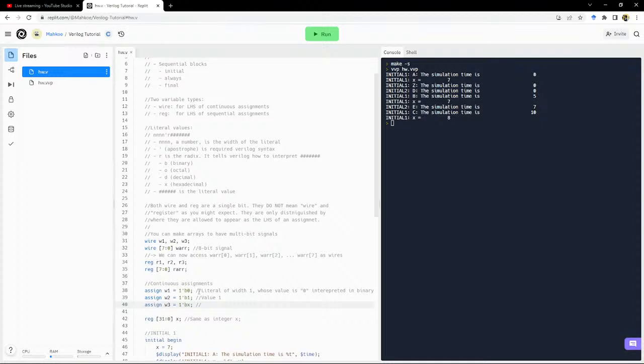Well, in Verilog, wires can have value 0, 1, X, or Z. Now, a 0 and a 1 mean exactly what you think they mean. They are just zeros and ones, just like in binary. They're just numbers. Nothing really to say about it. X and Z are special values in Verilog. X means undefined.